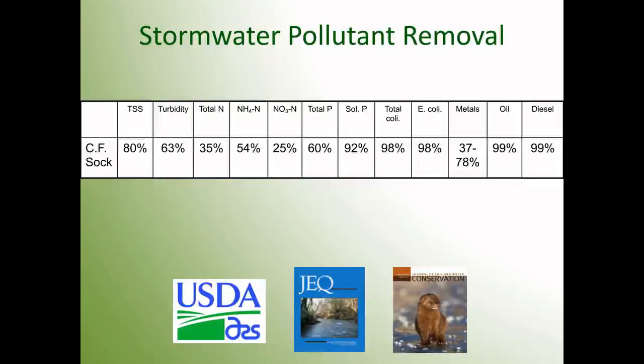But there are other organic materials and natural materials that actually have the ability to sorb or adsorb some of these soluble form pollutants that we find that are very prevalent in post-construction stormwater, whether it's on industrial sites or MS4 sites or anywhere in urban stormwater runoff. Examples include nitrogen species, phosphorus species, total coliform, E. coli, heavy metals.